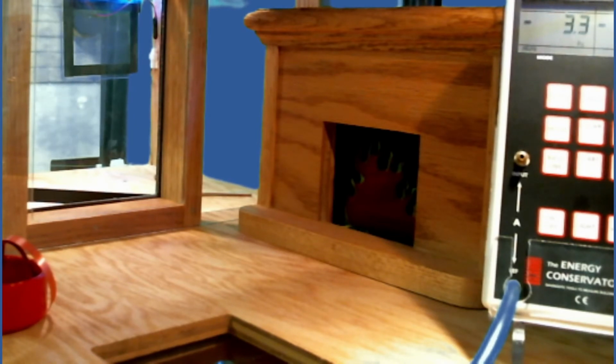The easiest way to do it is just look at the number. Some people will carry a manometer around. Or, most of the gauges now have a Wi-Fi or Bluetooth connection, so you can set your manometer in the CAZ and read that on your phone. So this manometer can be in the furnace room in the basement, and you could be opening the door on the other side of the house and read this number of the CAZ on your phone. So the easiest thing to do here is, if I open it, does it go back close to 0 or does it get more negative? Let's see what happens. If it goes closer to 0, which it did, that means it's making the CAZ better. So worst case is going to be with this door closed.